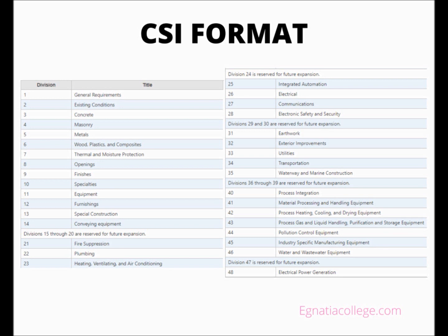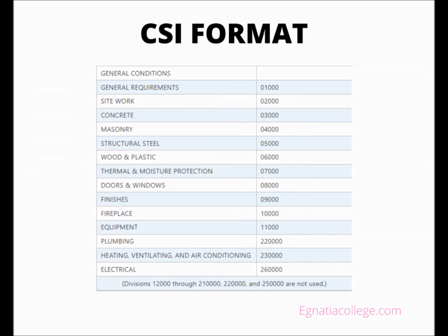To find a particular part of the construction project in the specs, use the following steps. Look up the appropriate division on the table of contents. Read the work included at the beginning of the division to be sure you have the right division. Find the description of the necessary materials right after the work included. Read the applicable subsection covering the work you want to do. Here are the specifications for lake house contents.